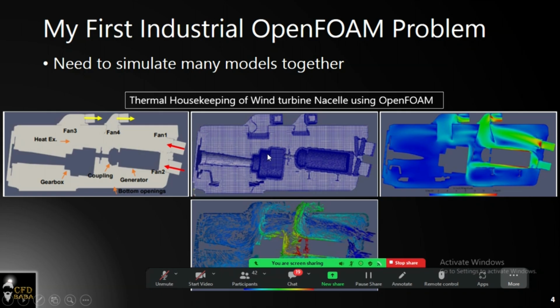So I started with learning the mesh first. I remember the first day when I meshed this CAD model, which is 3D and very complex inside, and it was quite a happy moment for me, and things didn't stop after that. The problem was that this coupling here was exceeding the acceptable limit of temperature, and they wanted a quick solution, without spending much money, on how we can increase the cooling of this fluid coupling.